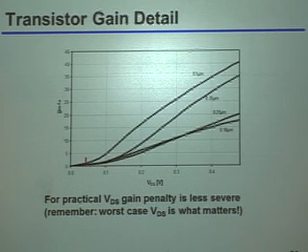And so the good news there is that if you really zoom in on the regions where the drain to source voltage is reasonably well constrained, meaning it's close to whatever that minimum value you'd like to use really is, now actually the picture doesn't look quite as bad. In other words, the actual gain you can get from a short channel device versus the longer channel devices doesn't tend to degrade quite as badly once you really constrain it to this more reasonable VDS range. Does this make sense to people? So this is, by the way, a silver lining, saying that, yeah, things are getting worse, but maybe not quite as quickly as people like to complain about.